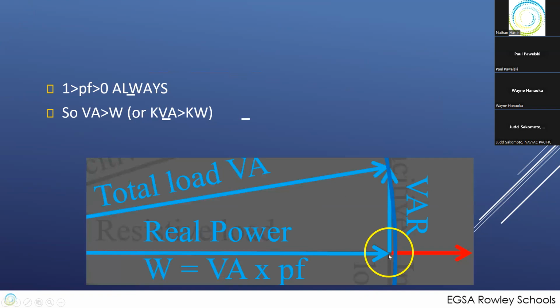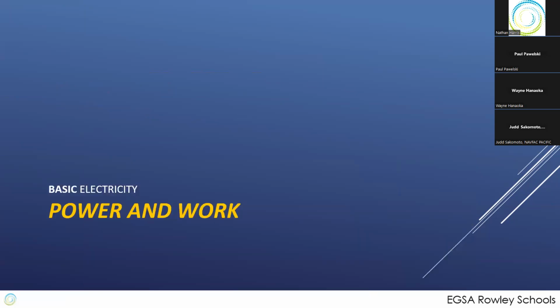This gap here between where the real power is at and where the circle arc is for the total power, that's your power factor. That's all that it is. It's not foam and beer, it's nothing magical. It's just what happens when the fictitious RMS voltage and amps we're using don't match up with the reality of the instantaneous power we can make from out of phase sine waves.